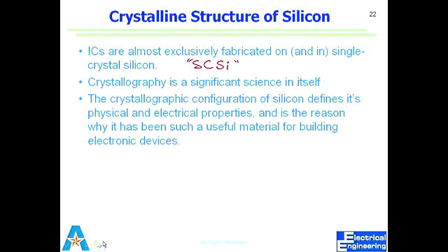Why don't I use metal directly, and why am I worrying about polysilicon? Because polysilicon has almost the same thermal behavior as silicon. It's different, but it can withstand high temperature. A metal cannot. So if I need to do some thermal process after I put conductive material, I cannot use metal there. Are you following me?